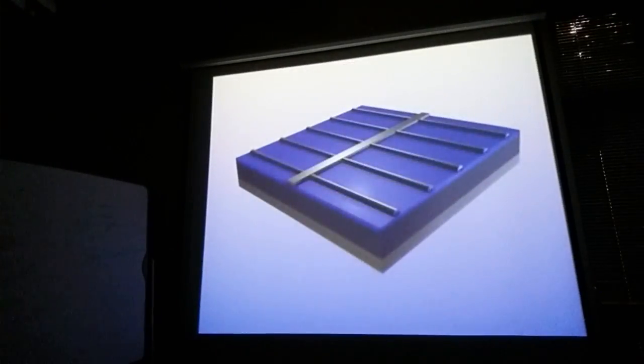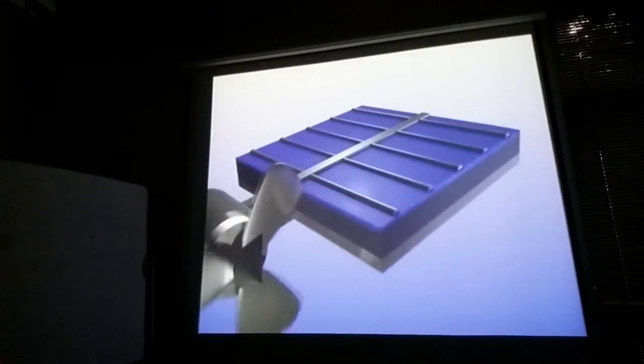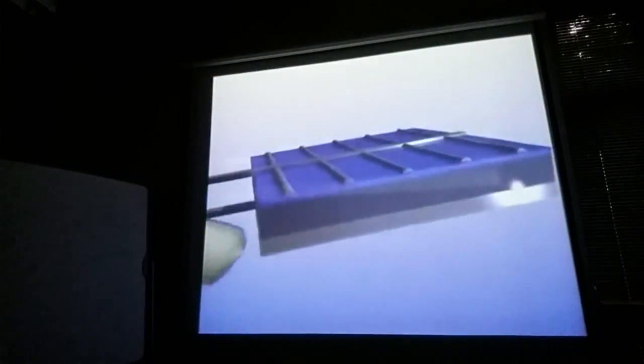Finally, front surface contacts are made to collect the electrons arriving from the junction. This grid is constructed with as few contacts as possible so that the p-n junction isn't shadowed too much. We can now power a light bulb or electric motor by completing the circuit. Our cell is complete. Photons of sunlight pass through the thin N layer.